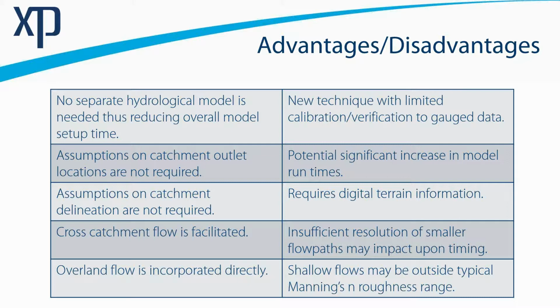One of the big downsides compared to hydrologic modelling is there's a big increase in runtime. So, huge increase. So you have to be prepared for that. Hydrologic models tend to run very, very quickly, in a matter of seconds or minutes, whereas these direct rainfall models can take quite a bit longer, of course. And even if you're just moving from a normal 2D model to a direct rainfall 2D model, you'll often see an increase, because basically every cell in your model is pretty well wet, and the number of wet cells will control the runtime or influence the runtime.